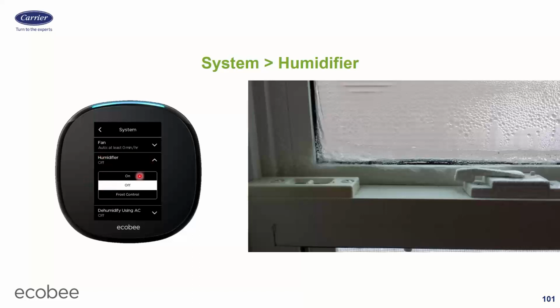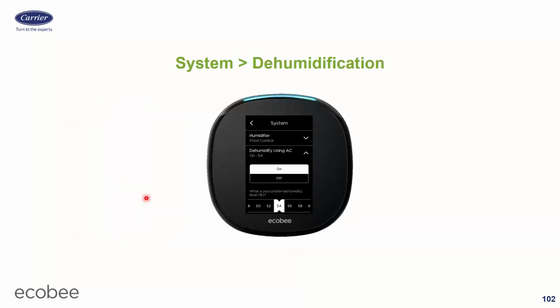So you have to come into this screen and either set it for on, which means it's going to run and it's going to ask you what set point you want. You're going to say, I want 27% or whatever it is, and life is good. Or you're going to put it on frost control, which means it's going to go on and off with its own outside air reference, right?